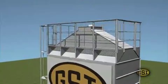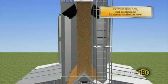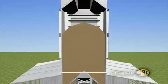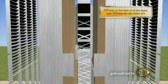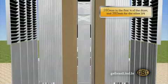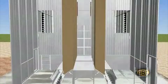Grain flow. The grain is inserted into the filling chamber at the top of the dryer where sensors control the load. The grain volume is distributed equally in the two drying columns, which begins at a lower thickness, producing a higher drying rate in the initial phase of the process, using the same drying temperature and ensuring the dryer provides greater energy efficiency.